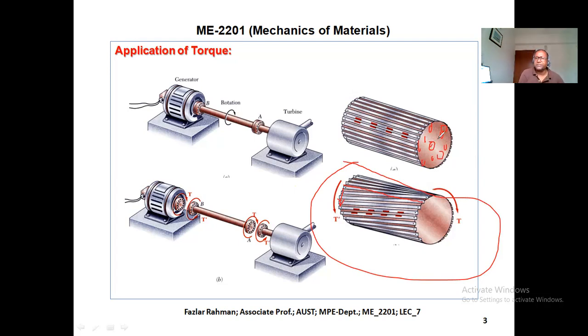So what does it mean? It means the inner pencils don't experience that much shear force. Similarly, in a beam, at the neutral axis, bending stress is 0. So from the center pencil, you'll see it is not rotating, it remains straight, but from the center to the outer pencils, you see they move further from the initial position.